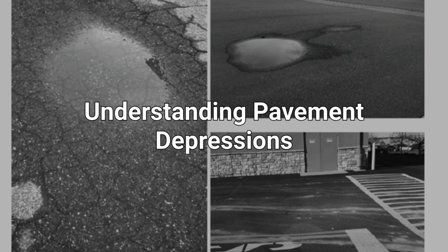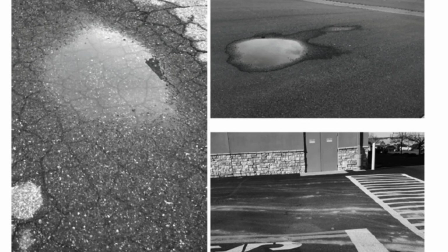Understanding pavement depressions. Depressions are localized lower elevations of the pavement surface, as shown in Fig. Due to subgrade settlement or frost heave, they are readily noticeable after rain fills them with water. They cause increased vehicle hydroplaning and accelerate the bottom-up fatigue damage process. Depression occurs due to frost heave or failure of subgrade, settlement resulting from inadequate compaction during construction. Depressions of less than 3/4 in, 19 mm, may be microsurfaced. Otherwise, they should be repaired by digging out and replacing the area of poor subgrade.